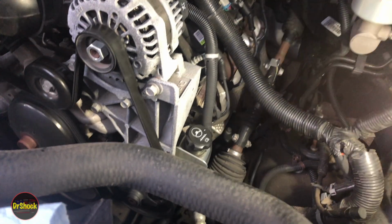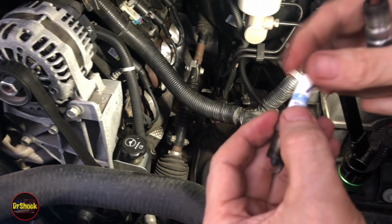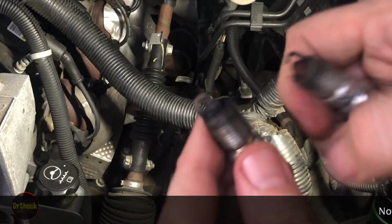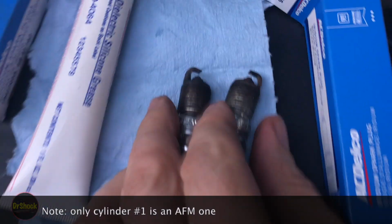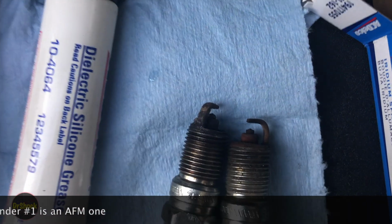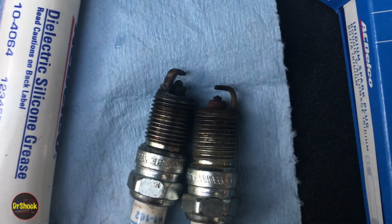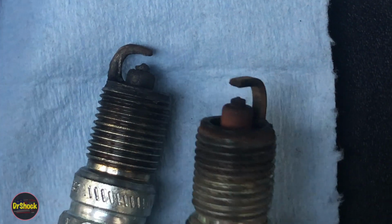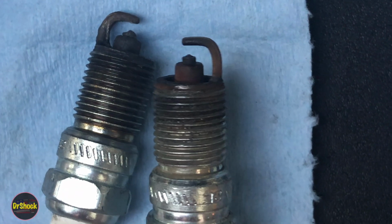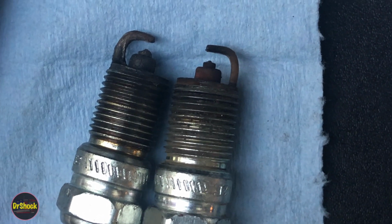On the spark plugs, we ended up only having a problem with 2. So we've got number 1 that you already saw, and number 3, the one right next to it. I thought maybe we can set it over here against this light background. I thought it was close enough, but all the others had a very clearly defined iridium tip, and so they were okay. I told you this is an oil burning engine, so you're going to have some evidence of that. But number 1 just really got worn off.